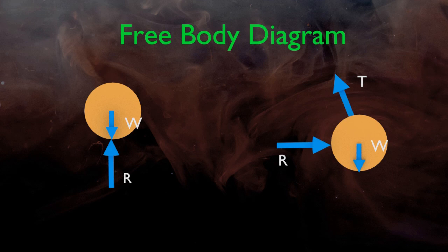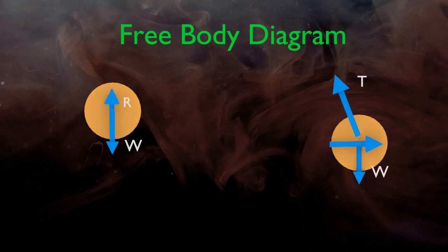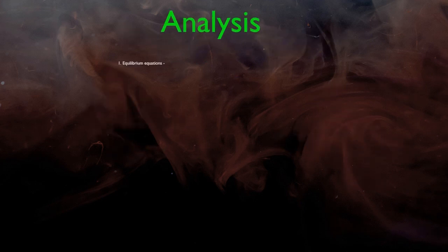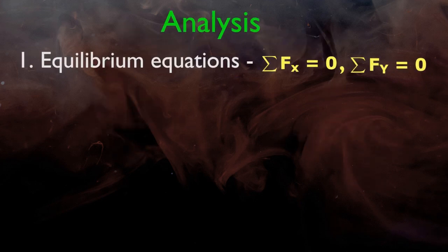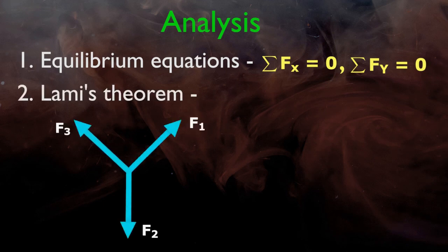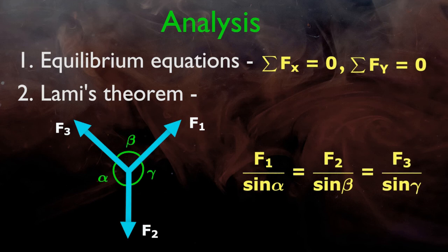It is a very important concept to identify various forces acting on an object while in equilibrium and also for analysis of forces. To analyze forces, rearrange all forces so that all of them meet at the center of gravity of the object and then use equilibrium equations and Lami's theorem, which states that if three forces are acting on a body, each force is proportional to the sine of the angle between the other two forces.